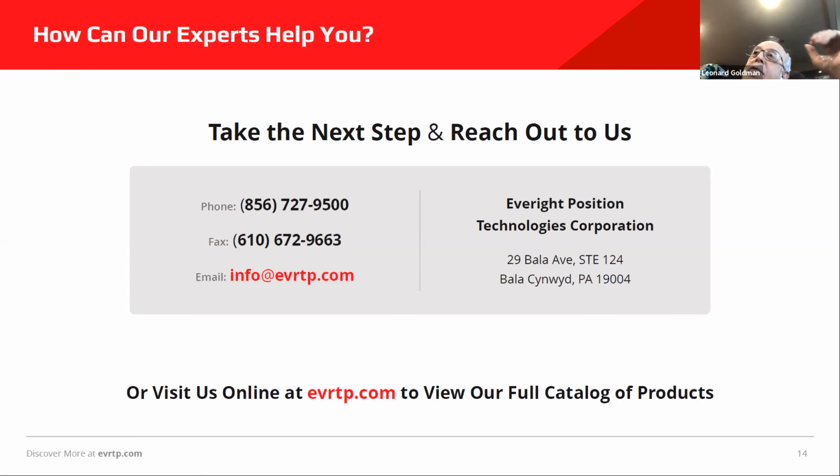To give you some numbers, with the capacitive sensors, you can have your alignment off by as much as plus or minus 0.2 of a millimeter, or 200 microns, which, if you know anything about alignments of optical encoders, they have to be less than 8 or 10 microns to get the highest resolution, to avoid that kind of tilt error.